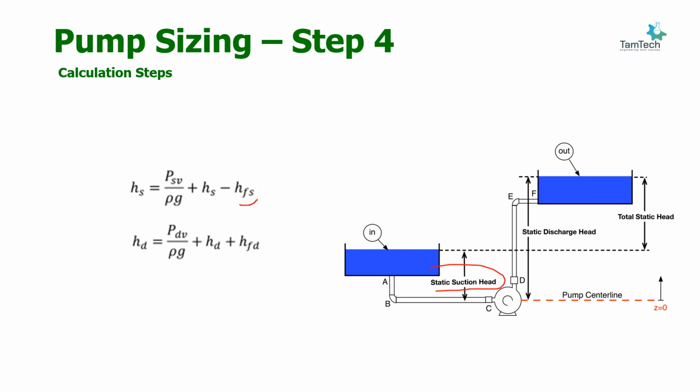We will do the same for discharge: discharge pressure divided by ρg, plus static discharge head, and plus head loss in discharge.